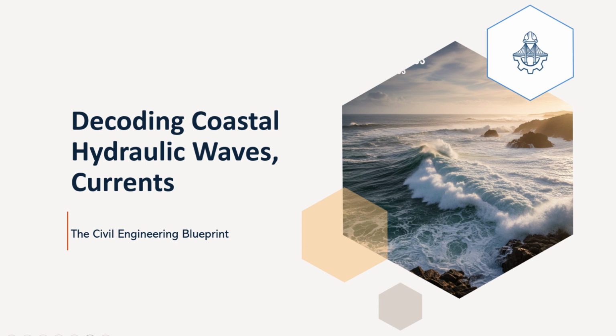Different parts of the same wave crest will travel at different speeds depending on the water depth they're currently in. The part of the wave in shallower water slows down more quickly than the part still in deeper water. This differential slowing causes the crest line to turn, often aligning it more parallel to the underwater depth contours, and thus often more parallel to the shoreline itself. It's a bit like a marching band, changing direction smoothly as different sections encounter shallower mud or deeper water at different times. This is vital, because refraction either concentrates or disperses wave energy along the coastline, affecting where erosion or deposition will be most intense.